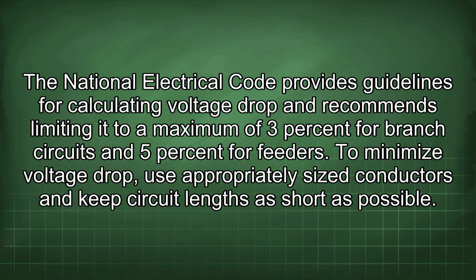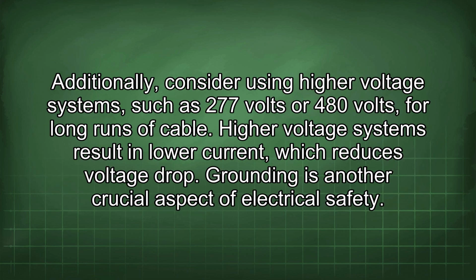To minimize voltage drop, use appropriately sized conductors and keep circuit lengths as short as possible. Additionally, consider using higher voltage systems such as 277 volts or 480 volts for long runs of cable. Higher voltage systems result in lower current, which reduces voltage drop.